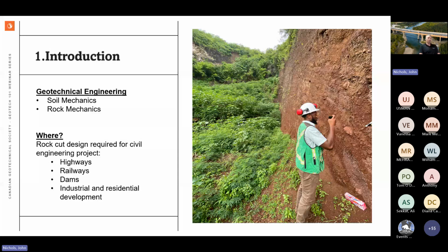So in that case, like rock, and even in that realm, rock can be really broken into weak rock slash soft rock and hard rock. The term weak rock is sort of defined by the International Society of Rock Mechanics, or the ISRM, as something between like 0.25 MPa to 25 MPa. And I've often heard these being called intermediate geomaterials, cemented soils, etc. So considering soil and rock, the transition, we'll use like a 1 MPa.